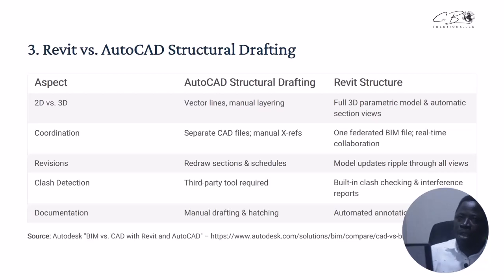Let's say for Revit Architecture, you delete a window from the plan. It will delete that window from the section, from the elevation, from the doors and window schedules, from everywhere at the same time. You don't even have to go there unless you have trust issues. Some people have trust issues. Even if they go to the ATM and the money comes, they still want to stand there and count as if it doesn't reach, they can question the ATM. Apart from those people, if you delete a step on the plan, forget it. It is deleted everywhere in the system.